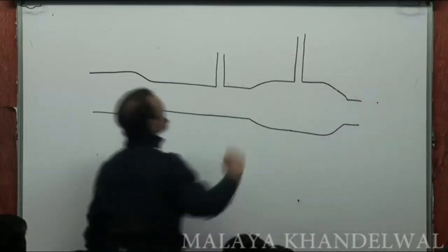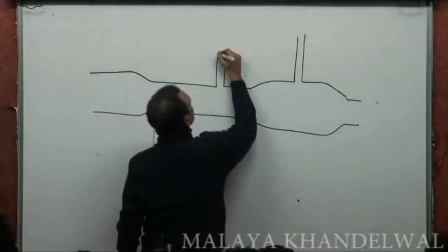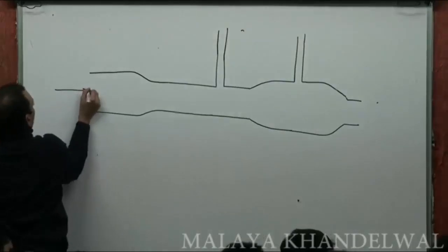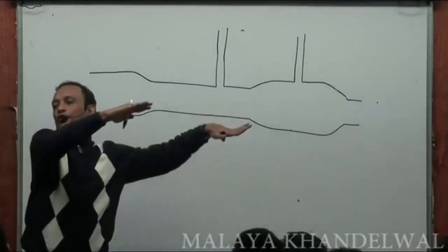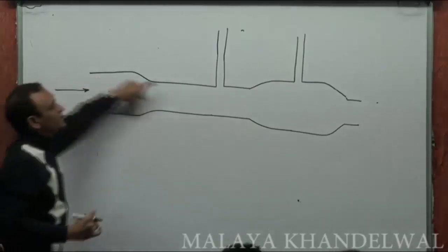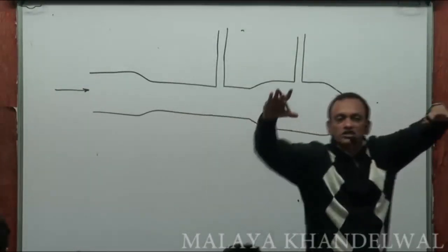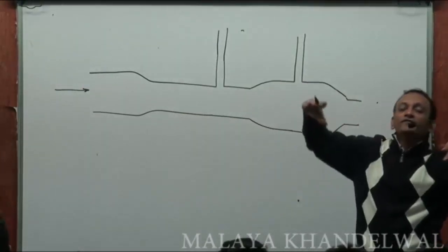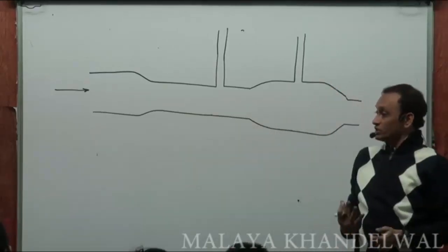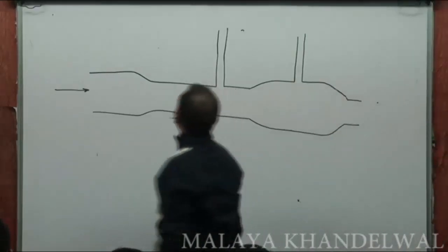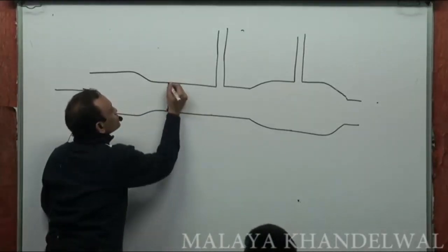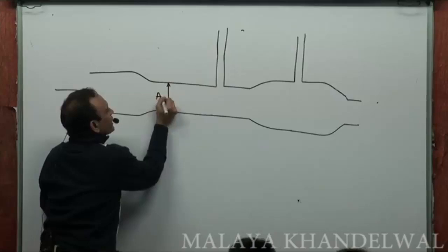An arrangement of this kind. It's connected in series with a pipe through which there is a flow occurring, and I want to be able to compute the volume flow rate. I connect this arrangement in series with a channel, with a view to compute the flow rate, cubic meters per second, through the channel. All right. Now, it has a narrow portion which has an area of cross section A1.